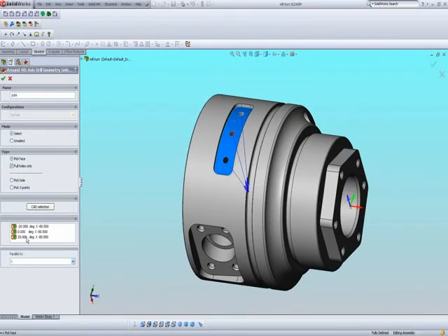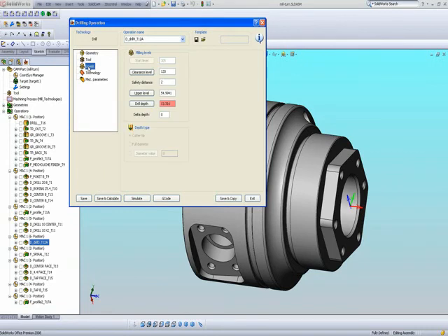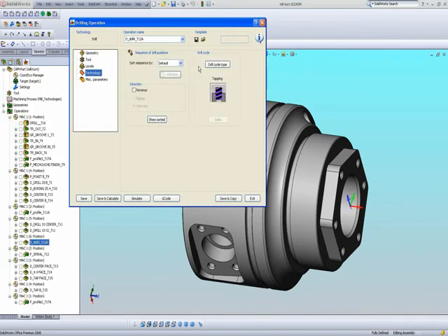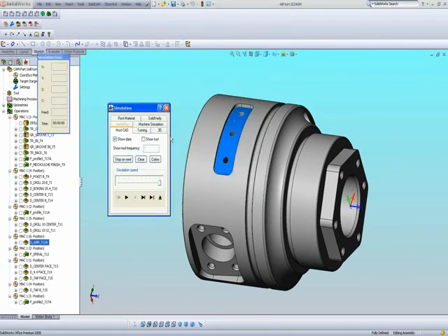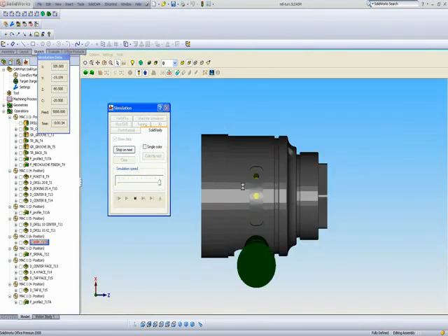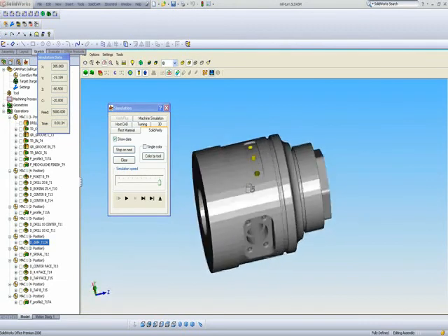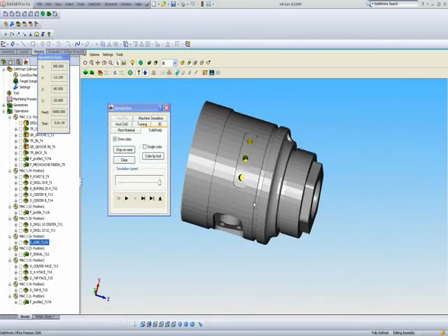And you can see their exact positions: minus 20 degrees, 0 degrees being the middle one, and 20 degrees. Again, I have my tool, my levels, technology, save and calculate, even though I make a mistake every now and then. Simulate, and if I do my solid verify simulation, you'll see that all of these holes are drilled out exactly the way they're supposed to be drilled out within one operation.